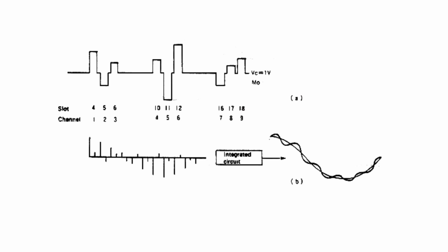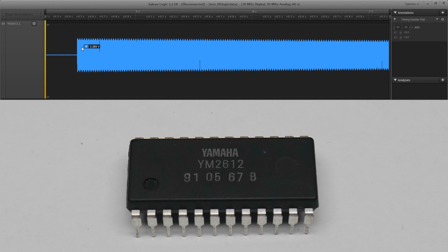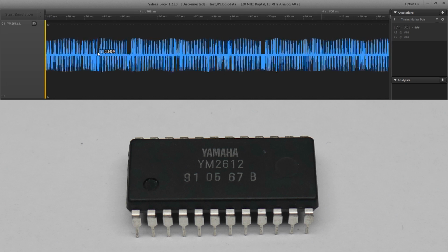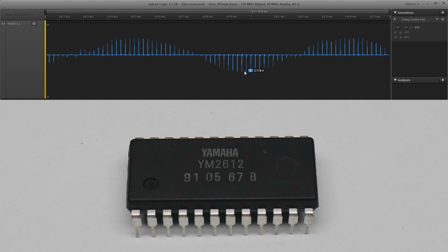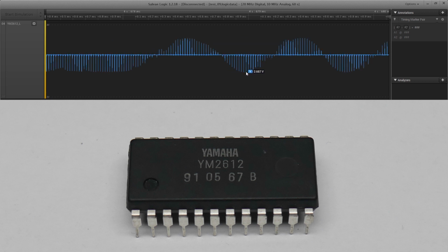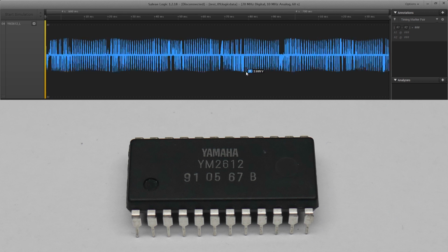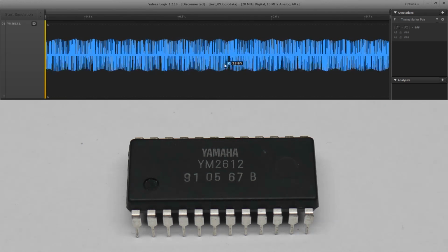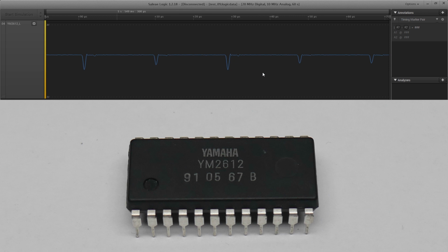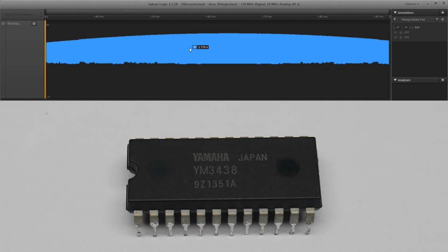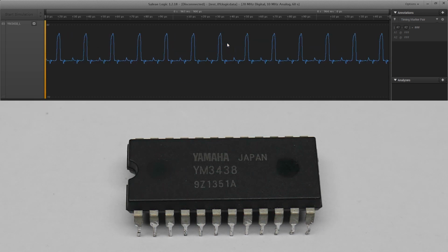So anyway, the OPN2 is pretty ill-suited as a chip to start making a bit accurate emulation. Not only is its multiplex signal pretty weak in terms of amplitude and width, it requires quite a bit of amplification to raise it to line level, and it's not trivial to do that without picking up tons of noise from all the digital junk in and out of the chip. The OPN2C is slightly better, but it still outputs on a multiplex stack.